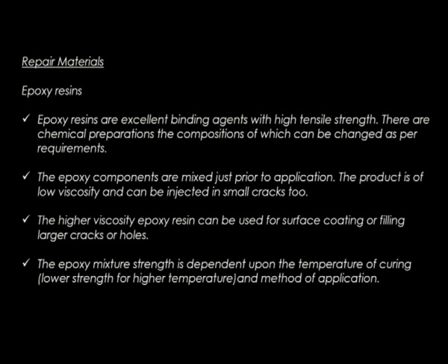Next is epoxy resins. Epoxy resins are excellent binding agents with high tensile strength. These are chemical preparations, the compositions of which can be changed as per requirements. The epoxy components are mixed just prior to the application. The low viscosity product can be injected into small cracks too.